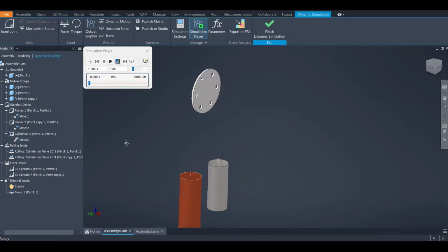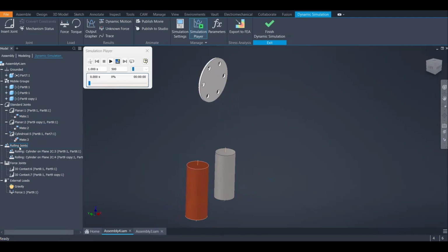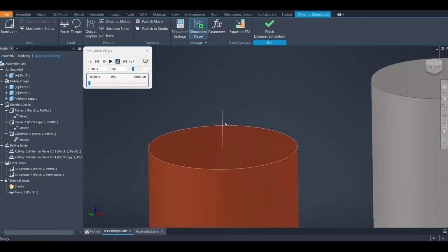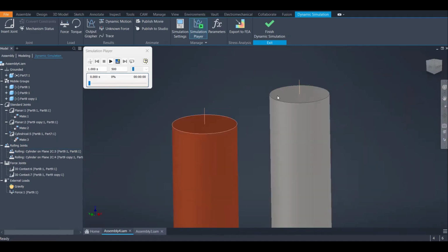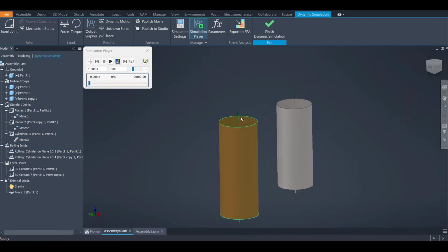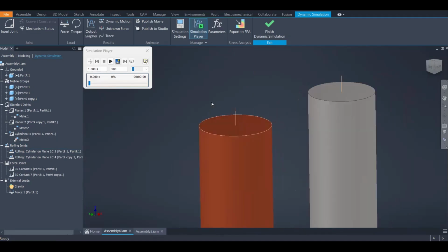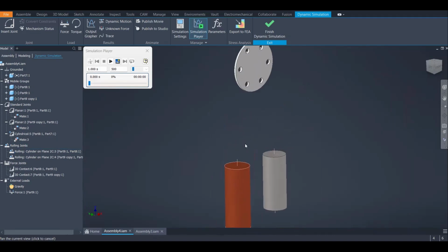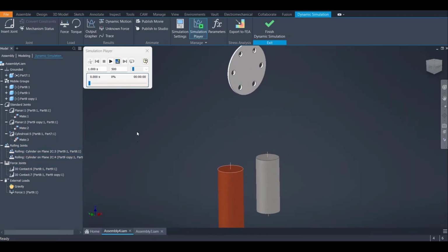So going down this tree at the left, we can see that there are some joints that are called rolling joints. So this is where the magic happens. There is a reason why I have this axis turned on both of the masses. It doesn't matter if the geometry is a square or something prismatic different from a cylinder. As long as we have this axis, that's going to work perfectly fine with the rolling thing.